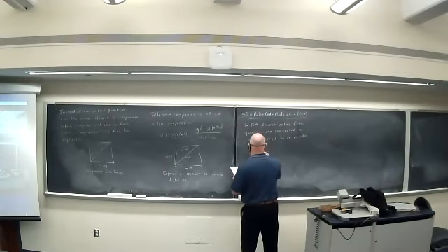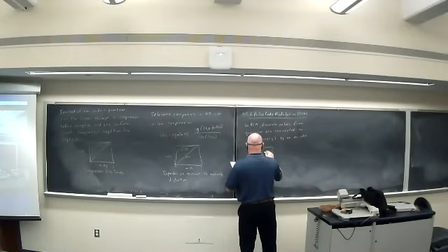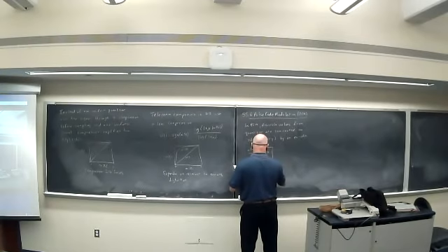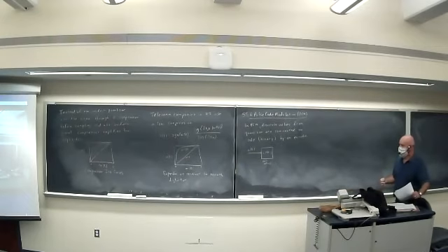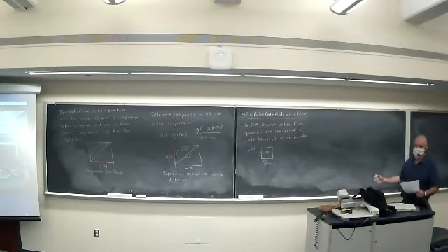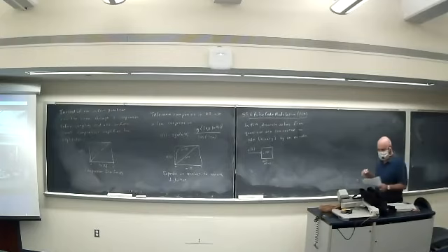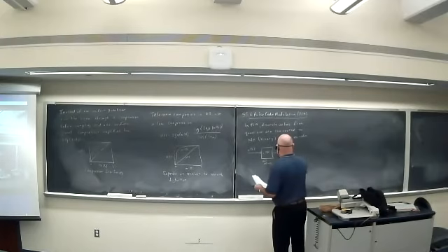And so my system now looks like this: I have my original baseband signal, and I run this through an anti-alias filter. Remember, that's going to remove all frequencies above whatever I consider. If I'm sampling at 20 kilohertz, I want to remove everything above 10 kilohertz, right? Above half my sampling frequency, so that I reduce the aliasing that occurs.